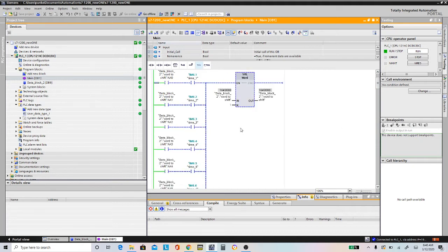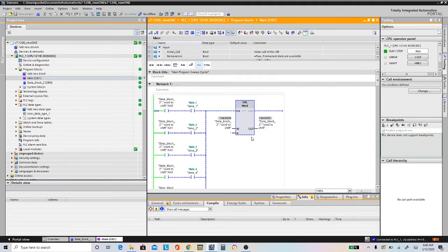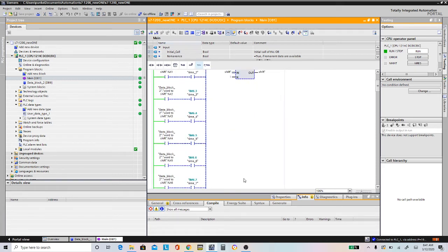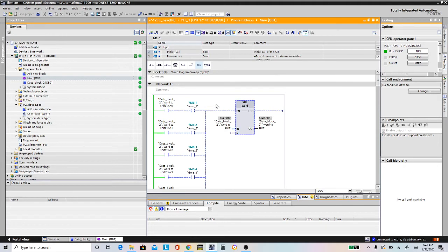Alright, this is one of the unique ways Denso taught me how to use a sequential shifting register. You have to shift left right here. Normally, people will have a bit right here and put a positive trigger, and every time it comes on, it shifts one time to the left.